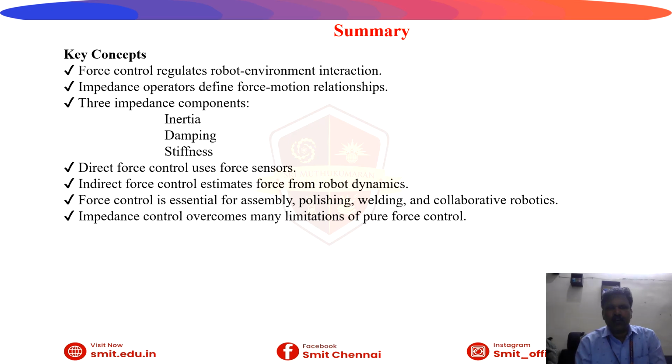Direct force control uses force sensors. Indirect force control estimates force from robot dynamics. Force control is essential for assembly, polishing, welding, and collaborative robotics. Impedance control overcomes many limitations of pure force control. So this is the summary of what we have discussed in today's class.